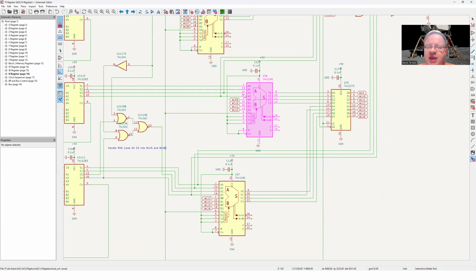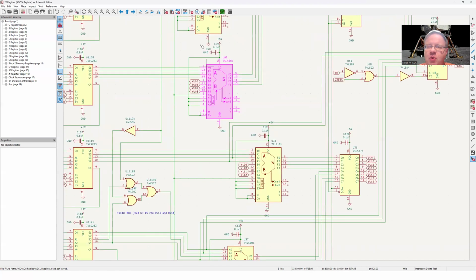But when you look at the fact that we'd have to do OR gates across all 16 write lines, and the 7400 series chips that have OR gates on them only have 4 gates per chip, we'd be using 4 chips containing OR gates to perform that logical function.